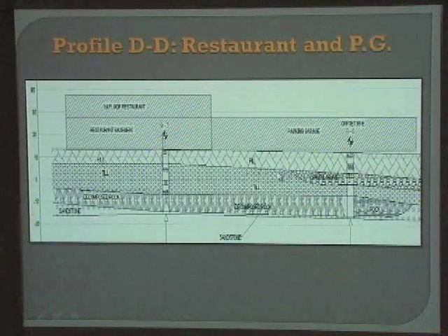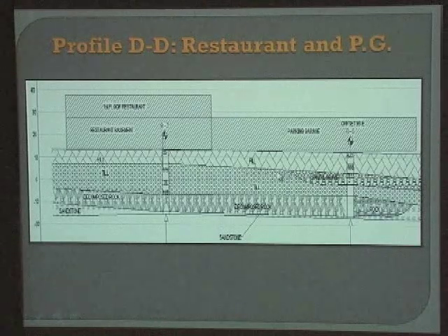We believe that the fill is dense enough to support our foundation, so we'll have surface compaction techniques using vibratory rollers, because this is a sand and gravel fill. And we'll have shallow footings in this fill layer just above the water table of 6.5 feet.